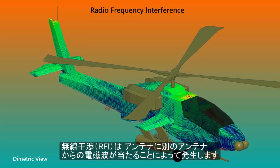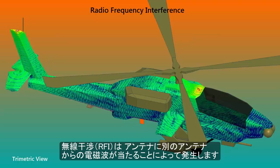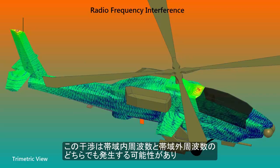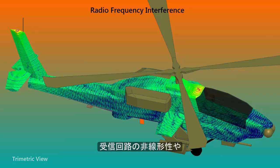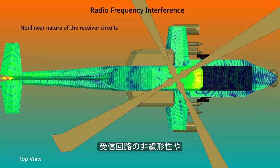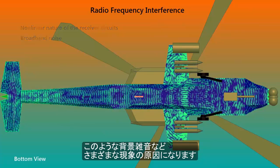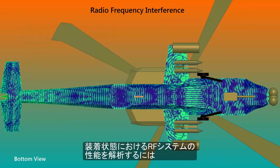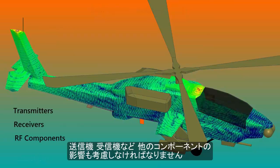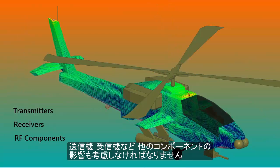Electromagnetic waves from one antenna reach the other antennas, leading to potential radio frequency interference, or RFI problems. This interference can occur at both in-band and out-of-band frequencies, resulting from multiple causes such as the nonlinear nature of the receiver circuits, broadband noise like the one you are hearing now in the background, and other phenomena. In addition to antenna interactions, we must also include the effects of the transmitters, receivers, and other components to simulate the performance of the RF systems in the installed environment.